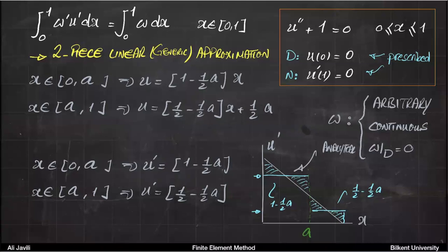So this is again somehow the way the finite element works. So maybe thinking of the derivatives is not such a bad idea. And it's not very surprising because you can see in your weak form, you are actually playing with the derivatives. So it's a derivative-based solution. Instead of dealing with the second derivatives, you are dealing with the first derivatives.